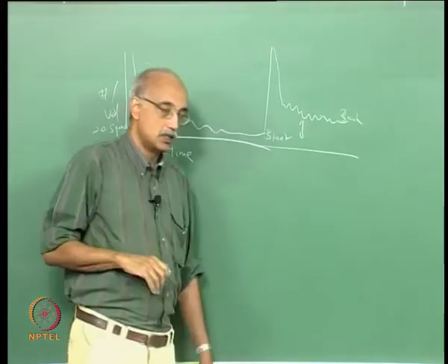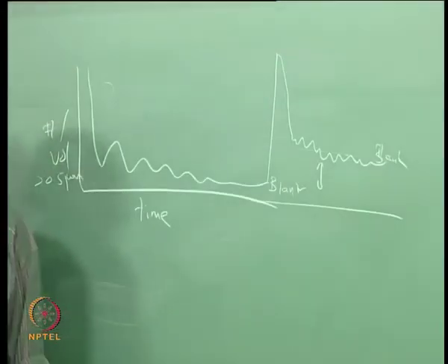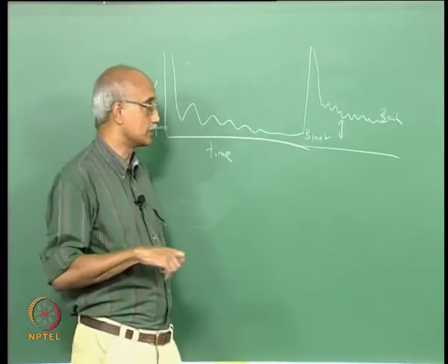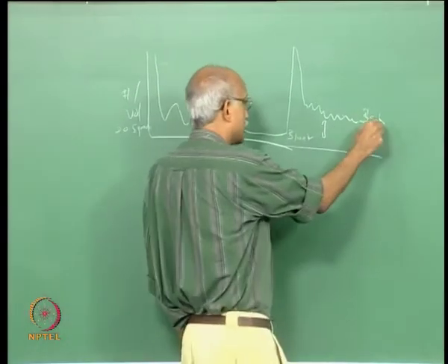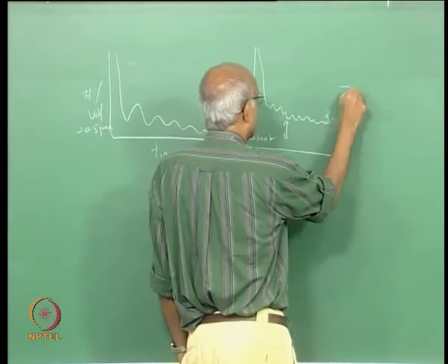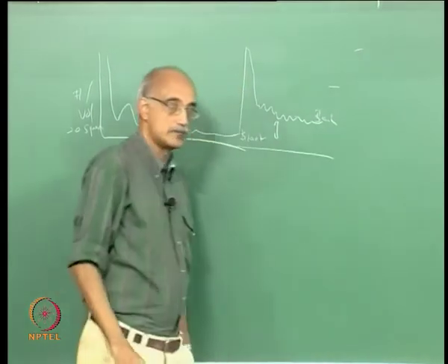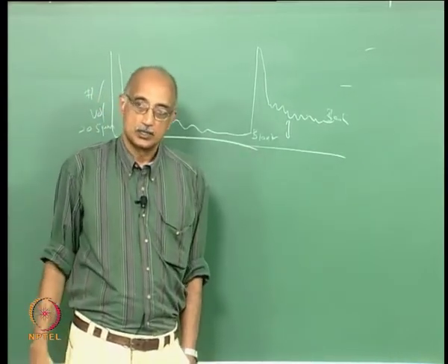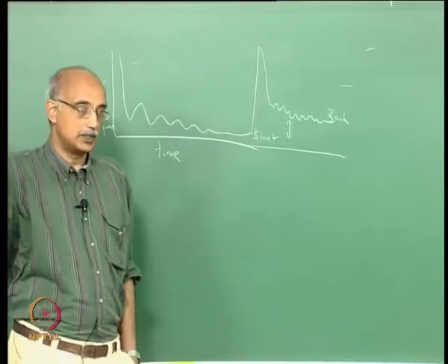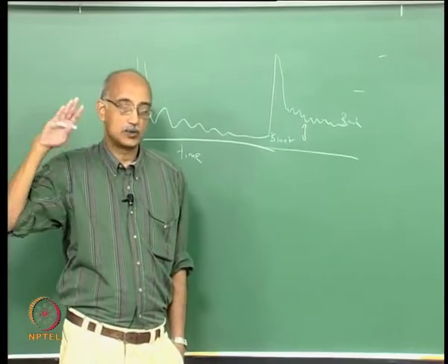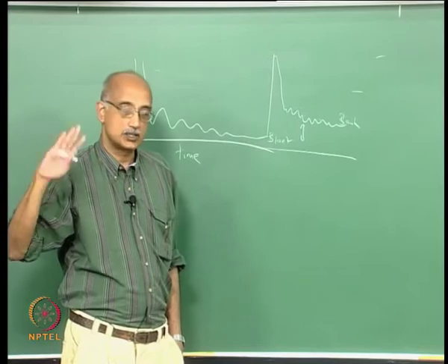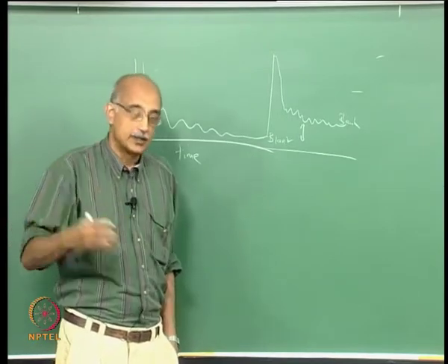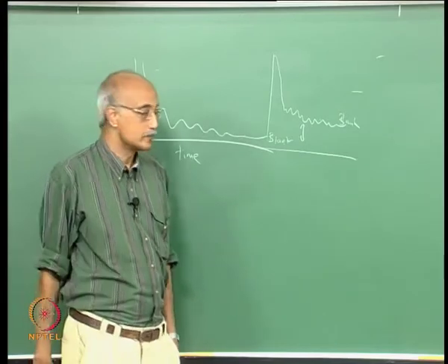So, this is the steady state contamination, or particles that are added by the wafer that is being cleaned through your system. If you keep doing this, this blank value will just keep increasing in magnitude for every cycle of pots going through the system. Eventually you will reach such a high value that you will say, I have to do something here. So, you will essentially turn off the system and again not run any wafers through, let it clean up, let it come back down.